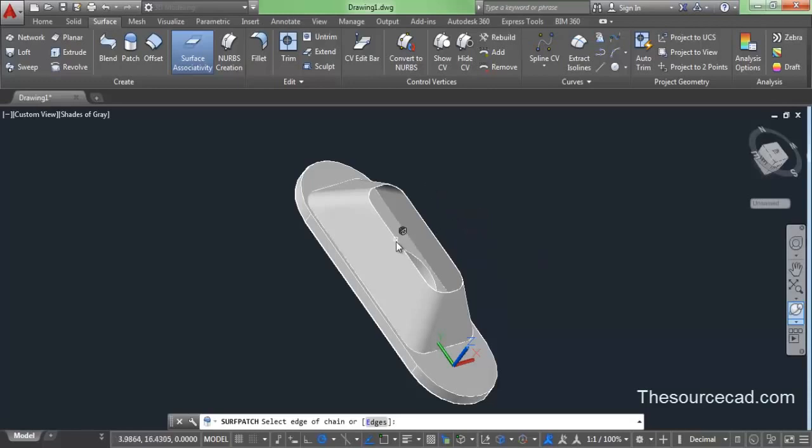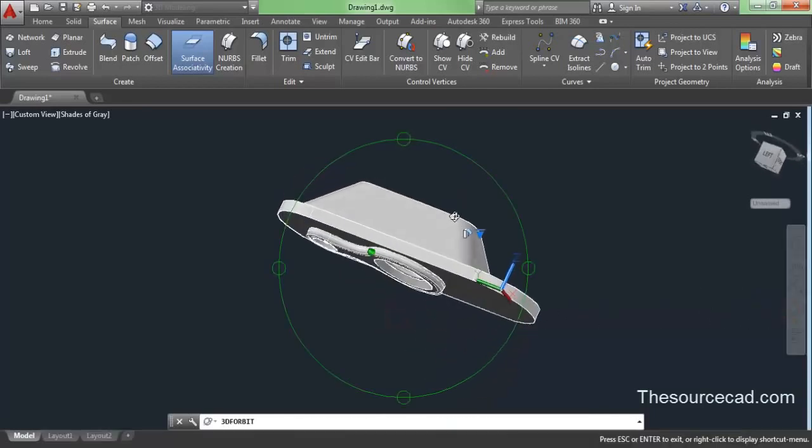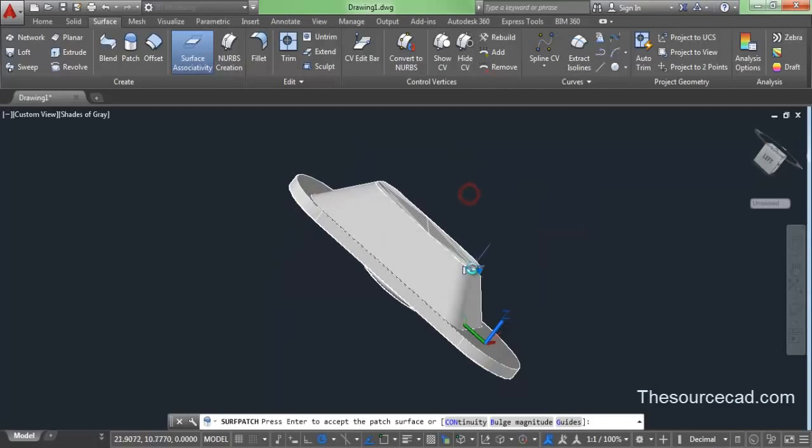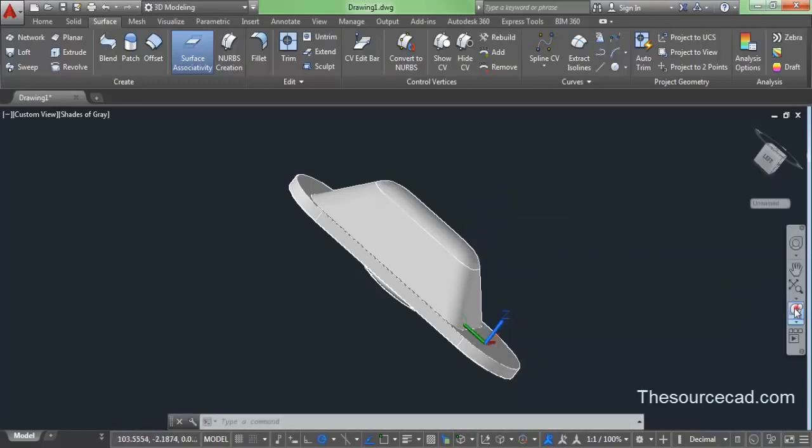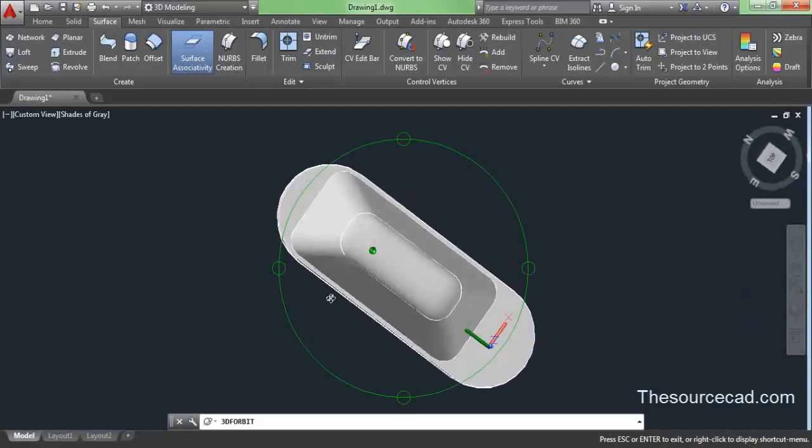So okay, I think it's not been selected. Now go on and select it again. Yes, make a selection now. Yes, here it is. Go on, press enter and click on this small arrow grip which you can see here. So click on this small arrow grip and change it to tangent and press enter. And here we have this closed profile.